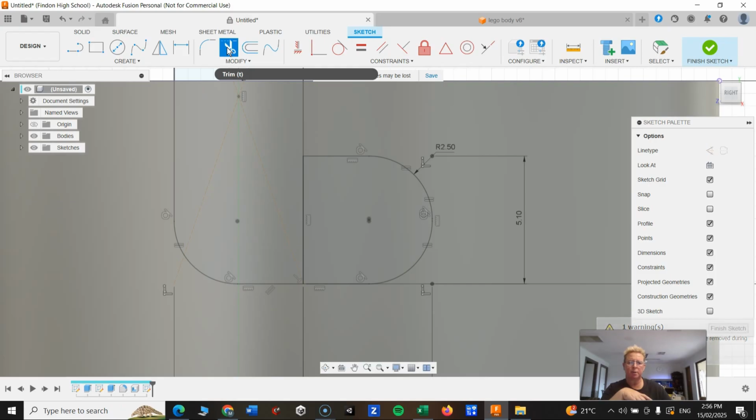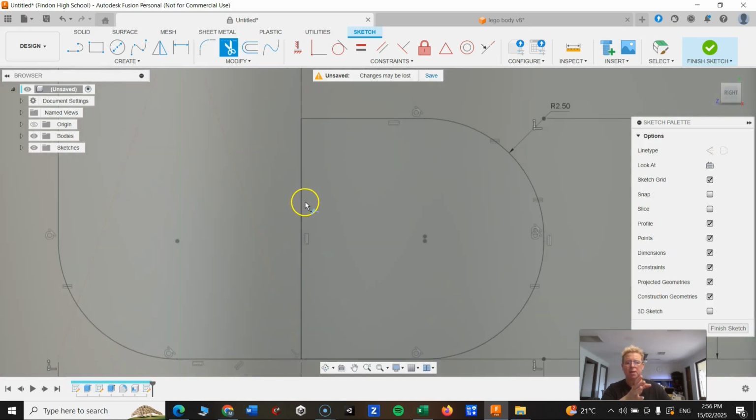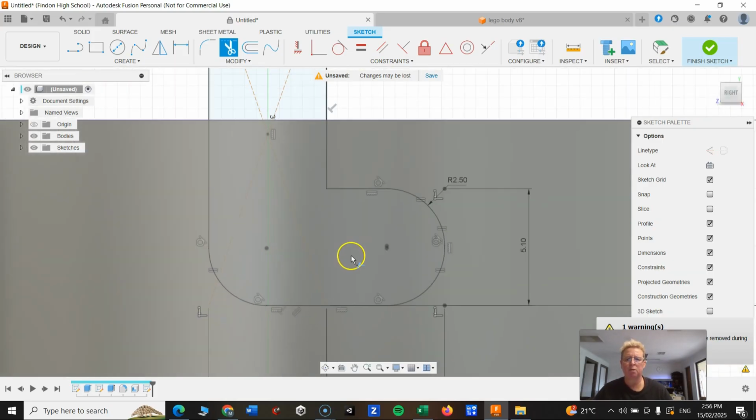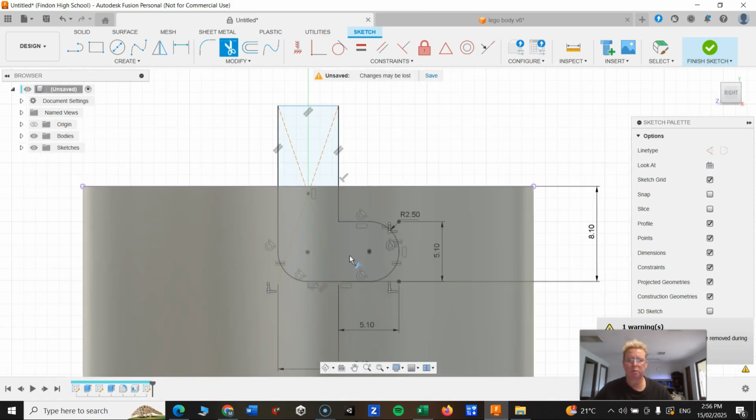I want you to select that pair of scissors, okay? And you'll recall we did 2 rectangles. We did the center point rectangle and then we did the corner rectangle. So this in effect is 2 lines. So we have to zoom, go over it and select it twice. When I click, you'll see my cursor has a little pair of scissors. When I click the first line, boom, it looks like it's gone, but there is still another line there. It's still red when I hover over it. If I click that again, boom, completely gone. There's my Christmas boot. Happy days, we are champions.